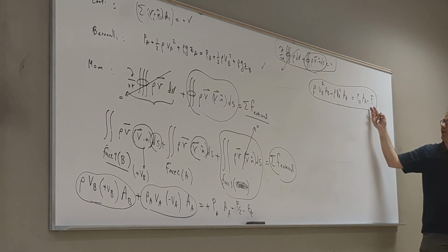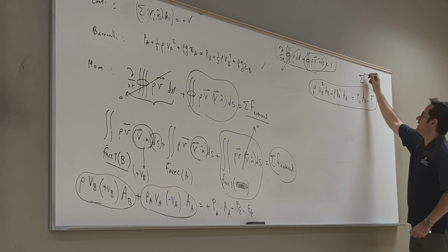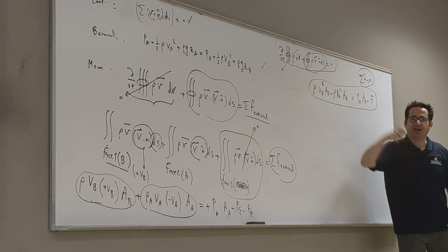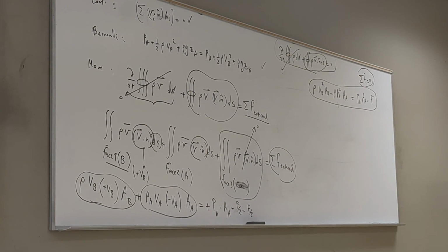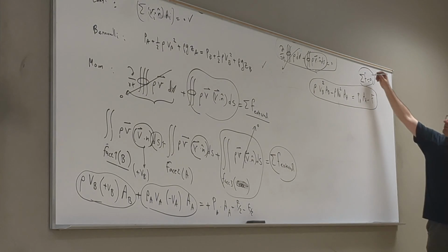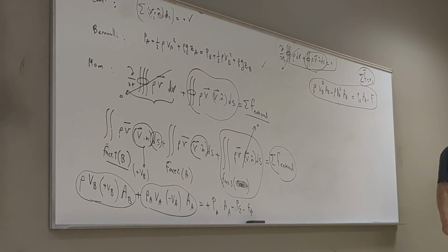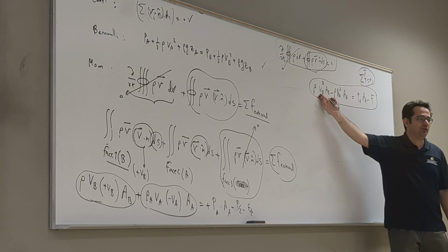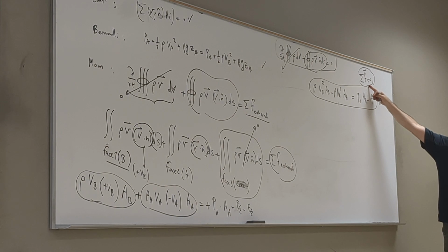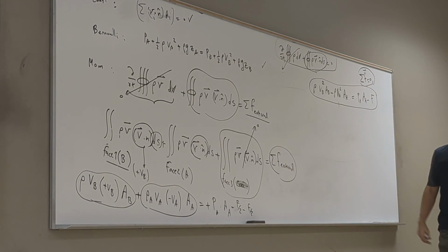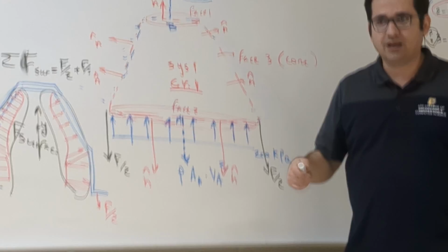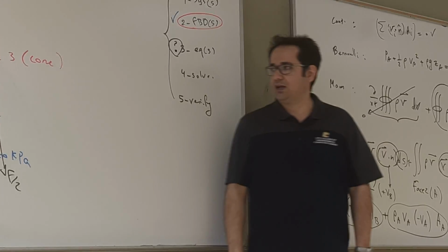If you bring this to the right, we're gonna get the same equation like vector statics, summation of forces equals 0. So that means we can consider these two as forces on the FBD, just like we did in vector statics. We draw the system and include all forces, and the sum of the forces must be 0, right? So even though these are not the actual load, if you put them on the FBD and do the summation, you will always end up with the equilibrium equation. Now you can do it this way, or you can just say my real loads are F and P, and I'll just expand the momentum equation to get to that.